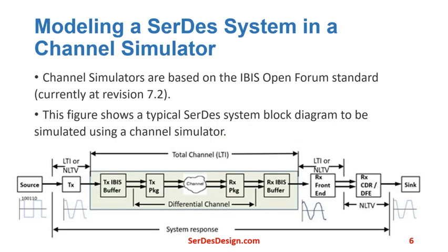Modeling SerDes systems in a channel simulator. Channel simulators are based on the IBIS Open Forum standard, currently at revision 7.2. This figure shows a typical SerDes system block diagram to be simulated using a channel simulator. This block diagram is generic for any channel simulator, but each tool has its specific way to represent this block diagram. The constituent parts of this SerDes system include the following: the transmit IBIS-AMI model.